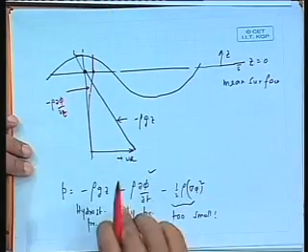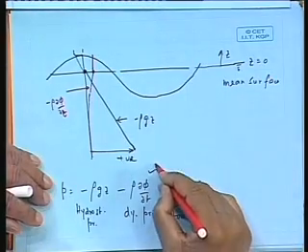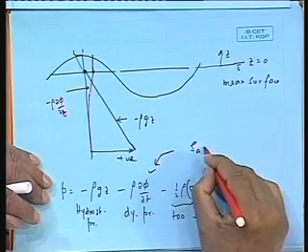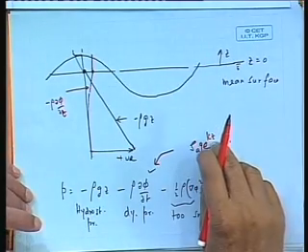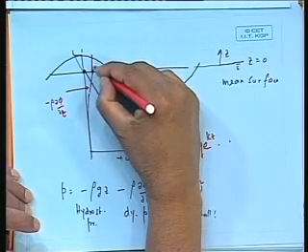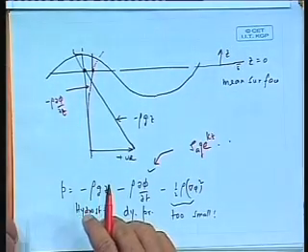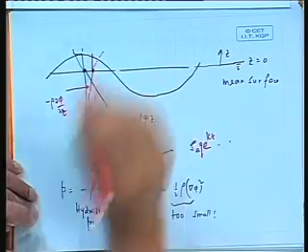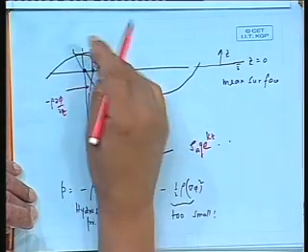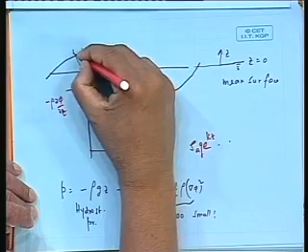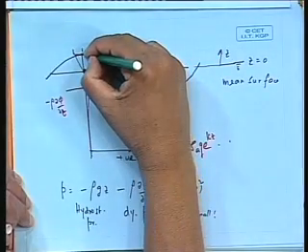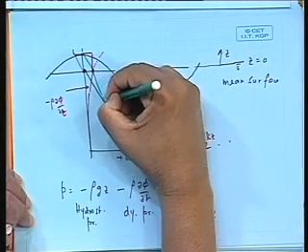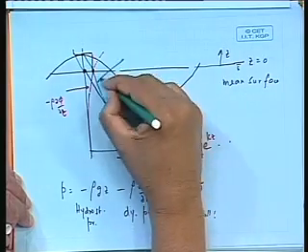Why constant? Because if you look at the formula for dynamic pressure, I will write down this formula. This formula is written as xi a e to the power of kz into whatever. It is having e power of kz. Now, if I allowed it to go like that, it would have increased, but theory says that it cannot increase. So, what is assumed in the theory is that this pressure remains constant in this region. Now, if you take the total pressure to be this and that, what happens? This is exactly the same as this, therefore, the net pressure becomes 0 here and here it becomes like this and eventually it becomes like this. This green line becomes my total